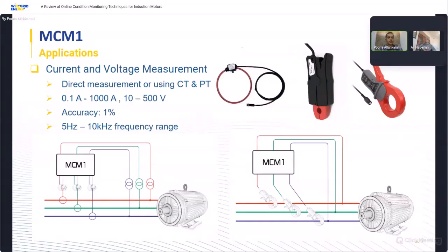For example, you measure the active power of the motor, the power factor of the motor, and some parameters in the power quality. So let's say, because you're saying 500 volt is the limit, that's good for pretty much all low voltage.